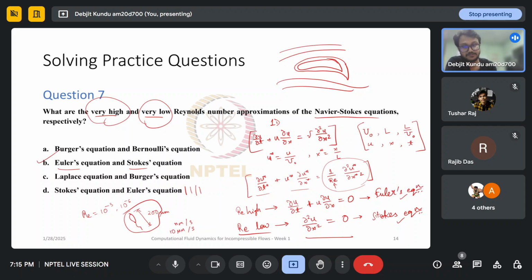and they have another cool feature. They are linear. So the only non-linearity in a Navier-Stokes equation lies in the convective term, which is sort of the inertia of the fluid, right? So if we ignore that, our equations become linear, and it turns out there are very simple techniques for solving linear equations. So that's what helps the scientists and engineers who are working on microfluidic applications as well as these very small microbial flows and flows within human cells and so on. There, this Stokes flow and Stokes equation becomes very important.